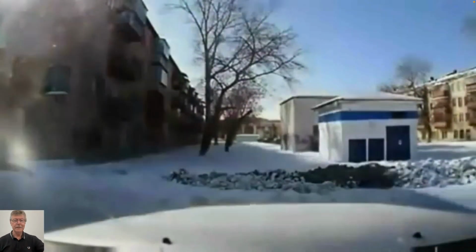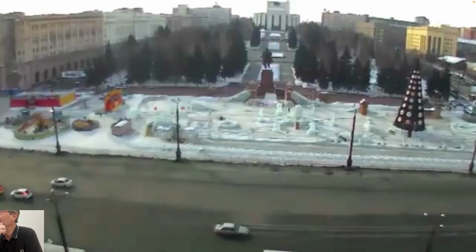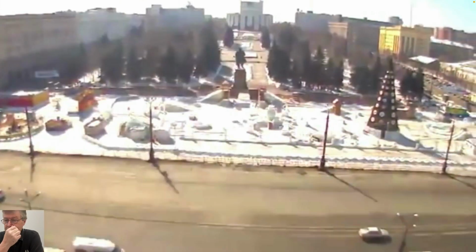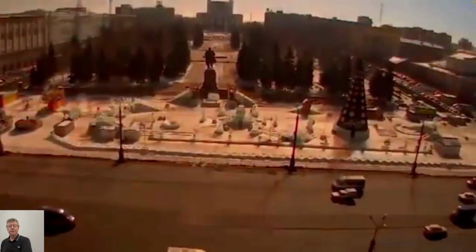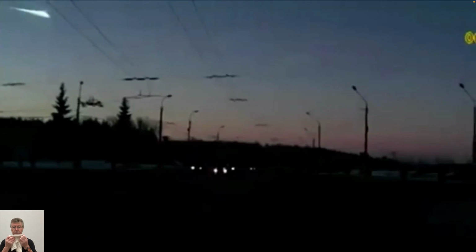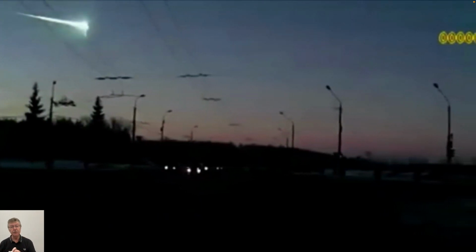Quite an amazing thing to see, really. I'm not sure why it's all that relevant to this class, but the F equals ma. Its transit through the atmosphere is controlled by drag, of course, which we haven't talked about yet. We've talked about only inviscid fluids, fluids that have no viscosity and therefore no drag. But I guess it will have pressure drag, pushing against something to move air out of its way and around it. And so that's a form of drag at very high velocities.